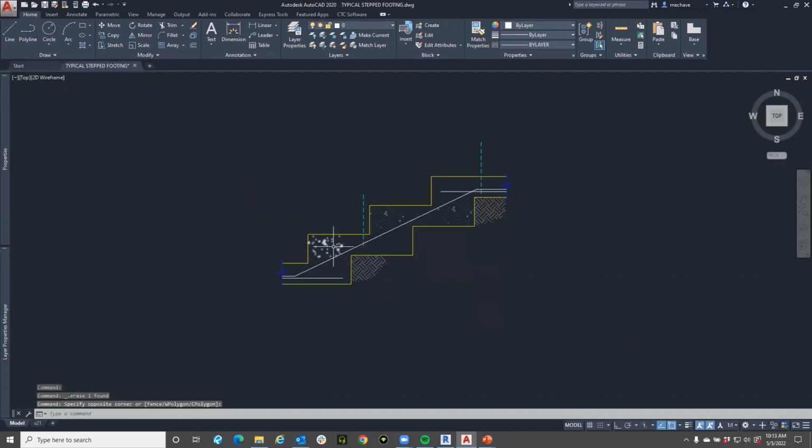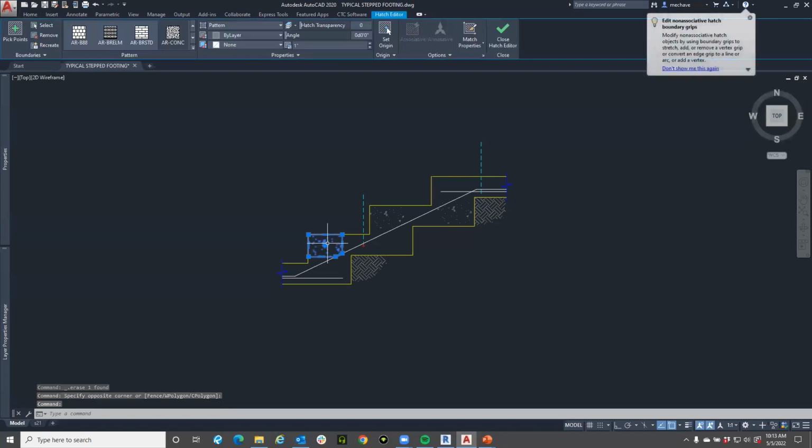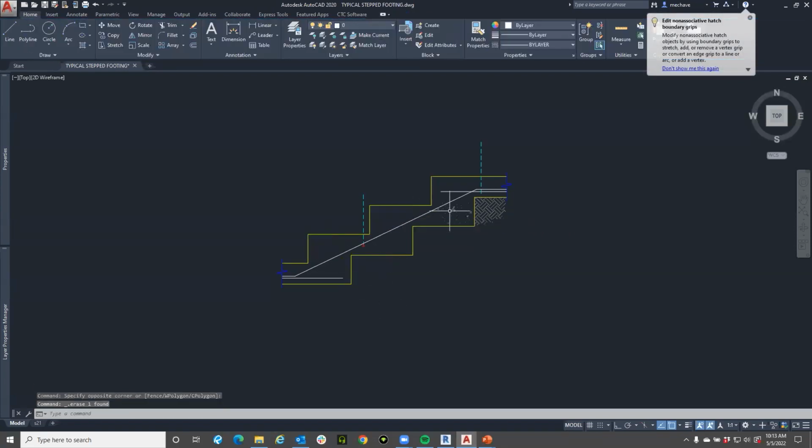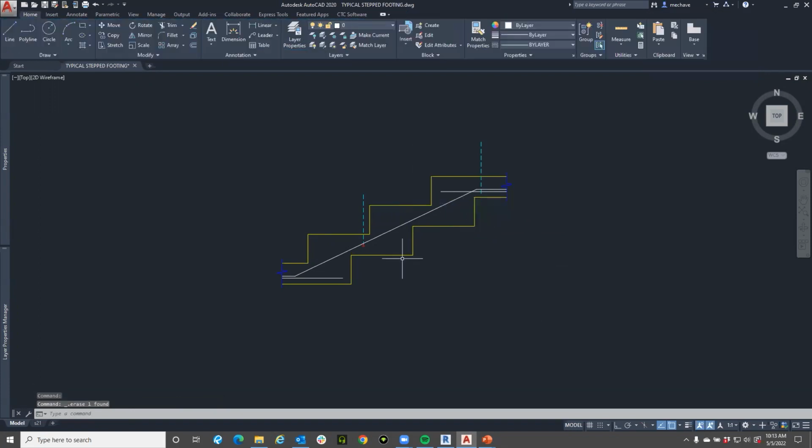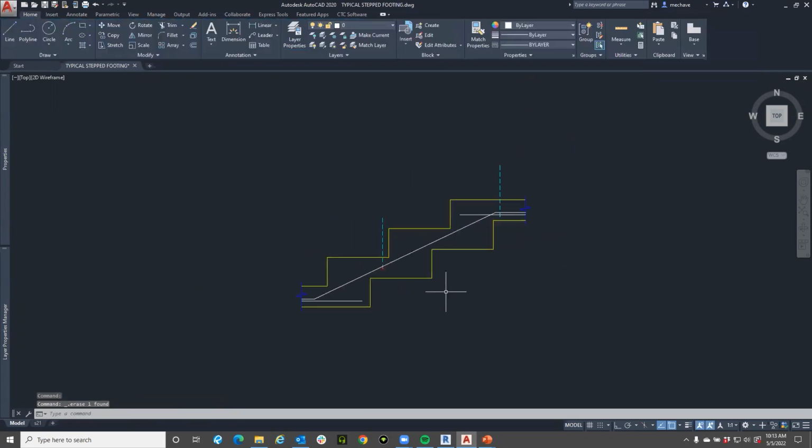And I just prefer, again, to each their own. I don't like to bring in hatch patterns because I don't want to have to deal with them. I'm going to make them filled regions anyway, so I'm going to make that directly in Revit. I prefer to just have my line data being brought over. I'll annotate it with Revit annotation after it's been brought in. But again, to each their own.